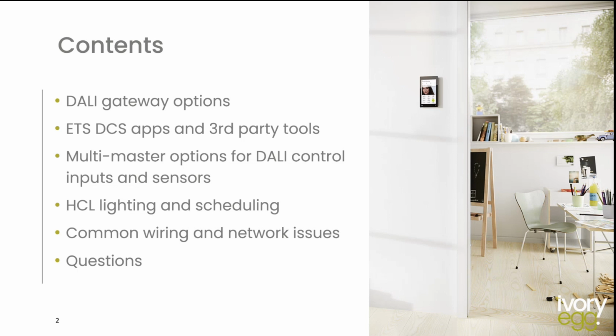And what that means is it's 240 volt connected. So this is a special certification for having 240 volt devices in Australia. So that's why we are limiting what we are looking at with that aspect. We'll also look at different ways of programming the DALI configuration and commissioning the DALI side of things. So there's apps and third-party tools.